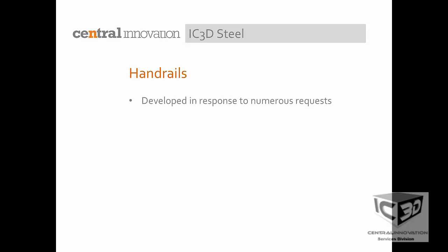Well, my personal experience speaking to customers out there, prospects, people in the know within the industry, there have been numerous requests, I should say, sorry, for handrails. So everyone that we speak to that's developing, say, platforms or anything like that, or any sort of structure, there might have been handrails needed for obvious safety reasons. So you can create obviously handrails within standard SolidWorks functionality using a sweep or some form of weldments or something like that, but we wanted something a little bit more automated.